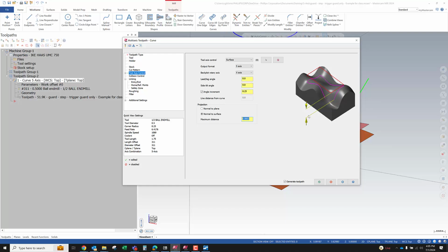The other thing to check sometimes is just if you're driving off the edges of a solid, you should be fine. If you know you've got lines, you should be okay. Splines sometimes have a weird mathematical definition where the curve is there, but it was created in a different plane or coordinate system, and there's some weird translation stuff going on. But yeah, curve is funky.